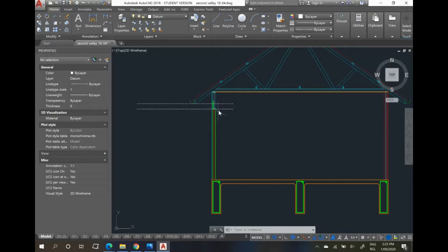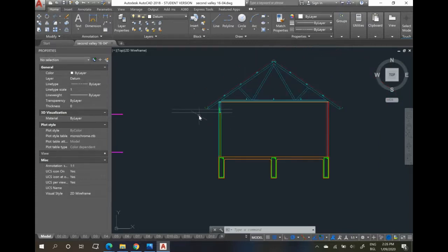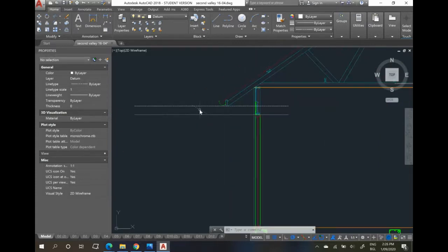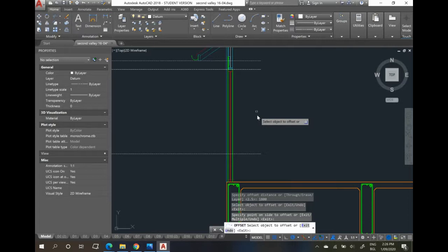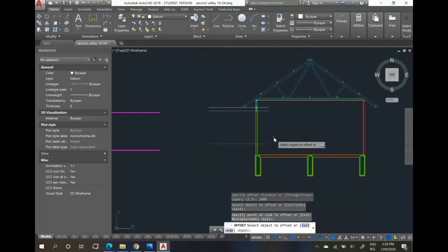We've actually got 2400 window head height on this one. But let's say we had an 1800 window, so I'll set our sill height down there. From our 2400 with an 1800 window, we end up sitting at 600 mil above the floor.